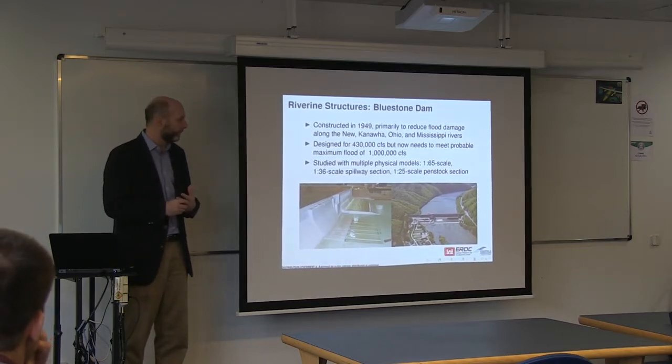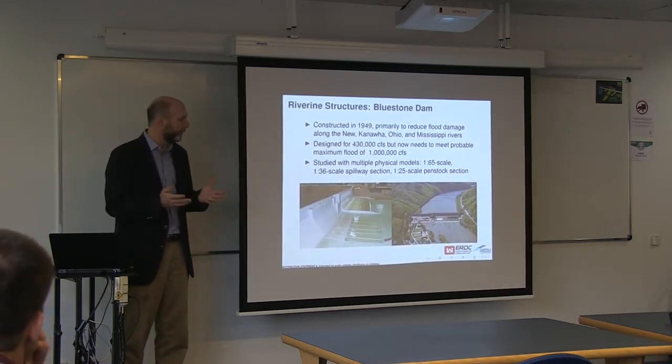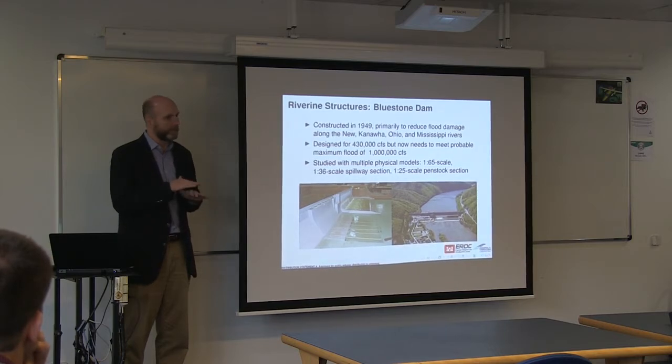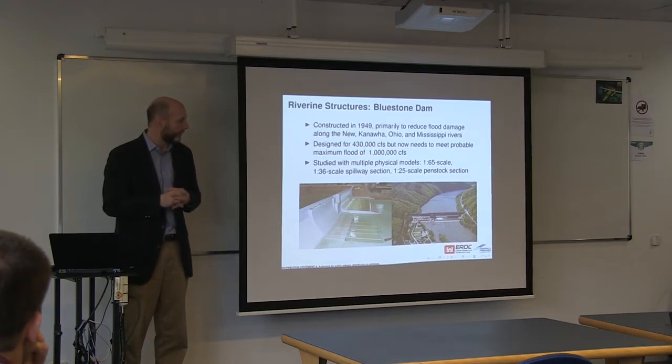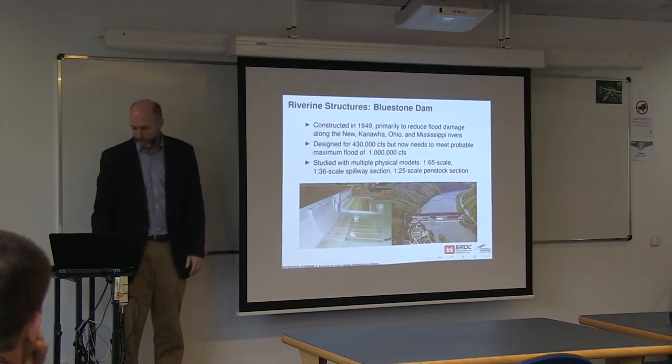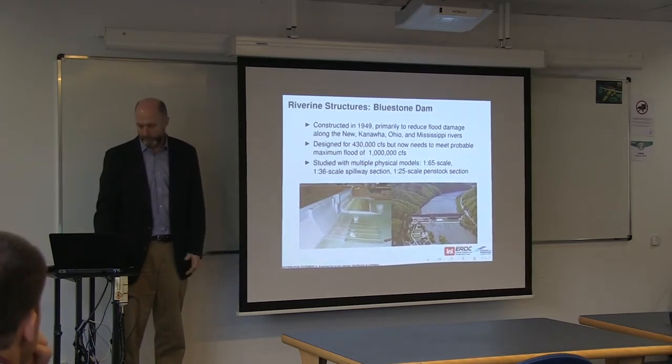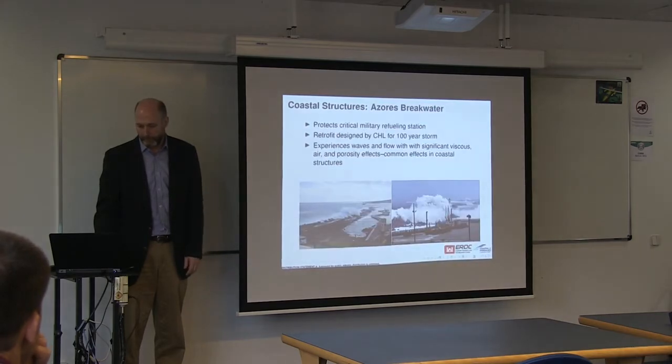There are, as we'll talk about a little bit, good riverine models for looking at sediment transport in 2 dimensions over large scales, but once you're dealing with a very 3-dimensional problem, the evolution of that scour is more difficult to model, obviously, in 2D, so you really need to resolve the 3-dimensionality of it. So that's one of the motivations.